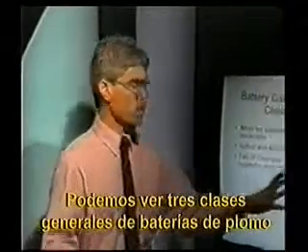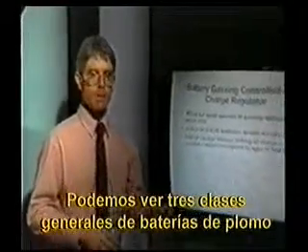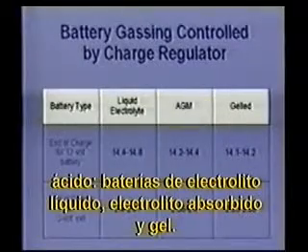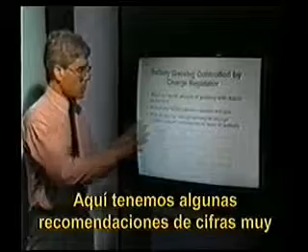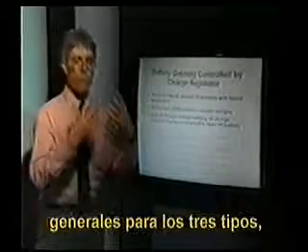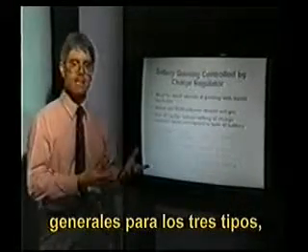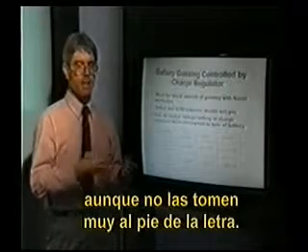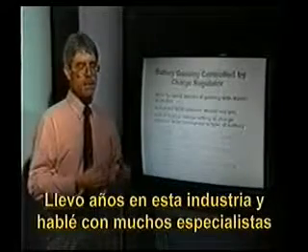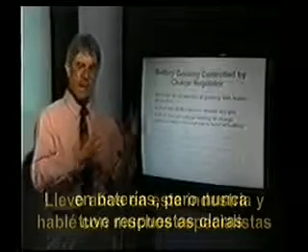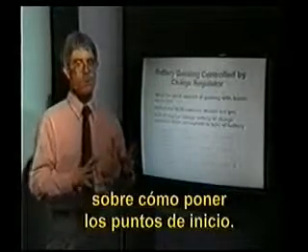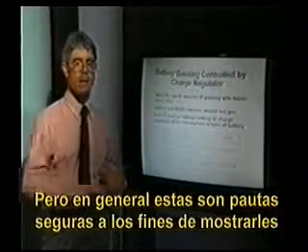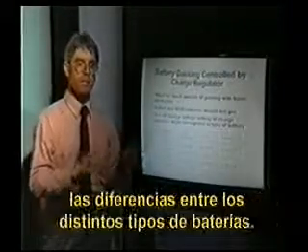We can look at three general classes of lead-acid batteries: liquid electrolyte batteries, absorbed glass mat, and gel types of batteries. In these three cases, I've drawn out some very general recommendation numbers. You can't take these numbers to be hard and fast. Over years of dealing in this industry, I've talked to a lot of battery people, and I have never gotten real straight, clear answers on exactly how to set the set point.